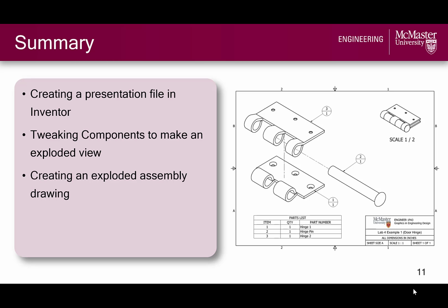This wraps up this video on assembly drawings, where we have learned how to make a presentation file and tweak components to make an exploded view. We then used that exploded view to make the drawing that we see to the right of this slide, complete with a parts list and balloons.